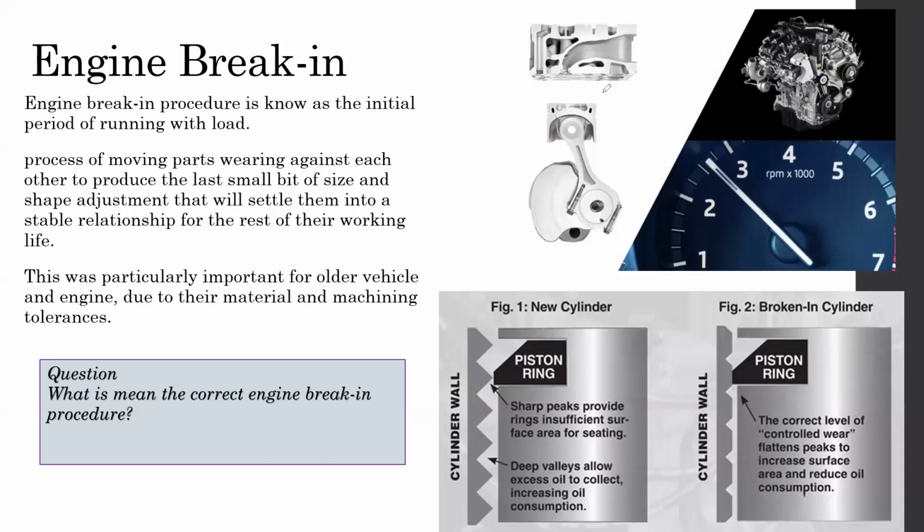So in order to achieve this smoothness on the engine cylinder wall, we run the engine at a constant low rpm without higher loads. If we add higher loads, because of the higher compression and higher speeds, the piston tends to twist and slap. To avoid these issues and to keep the engine temperature at a constant level, the engine is driven at a lower rpm for a certain amount of mileage.